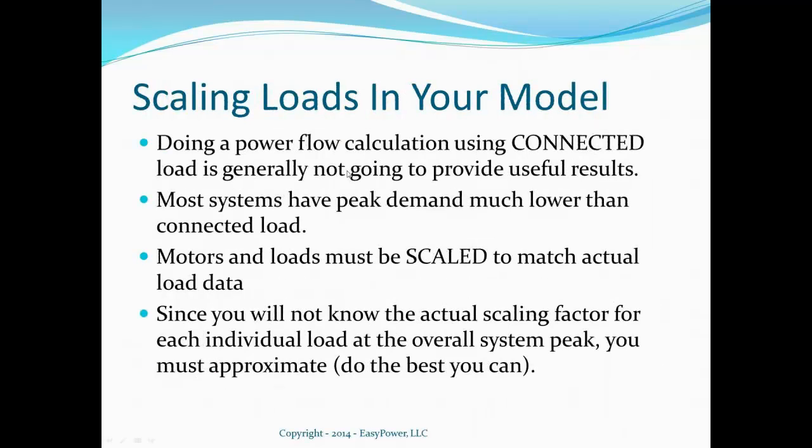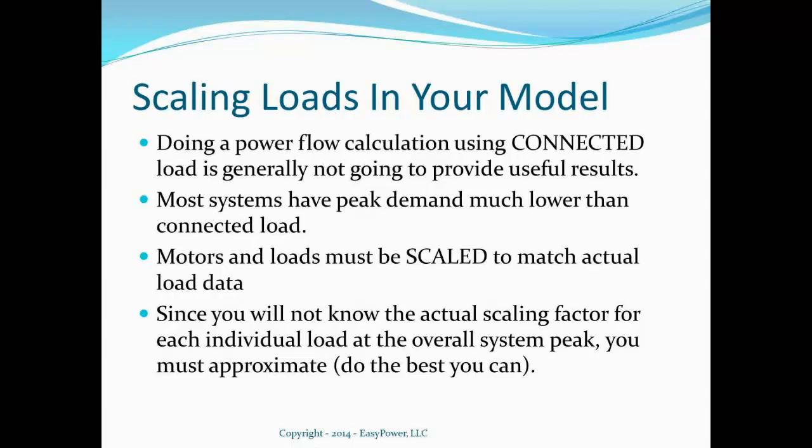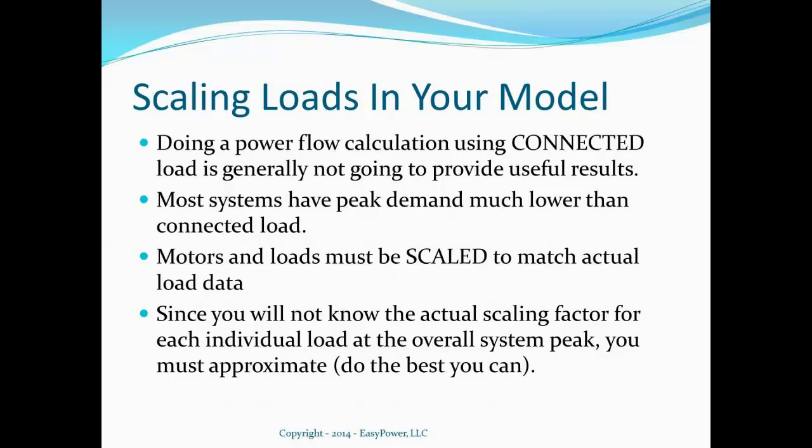All right, let's talk a little bit about the nuts and bolts of scaling the loads. As we've said, if you just run power flow on your model using the connected load, everything running at 100%, it's probably not going to tell you all that much because your system's not going to run in that condition. So you need to have some actual load data, and then scale the loads to match the data that you have.